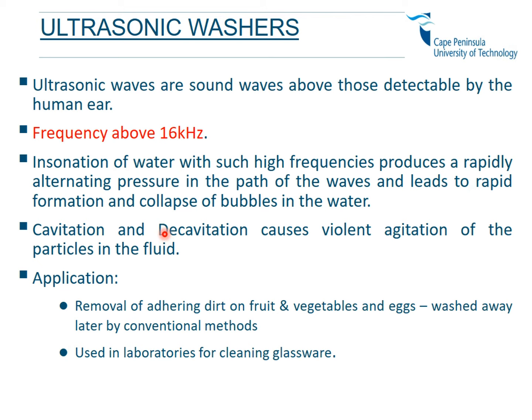The last method that we'll talk about is ultrasonic washers. This method makes use of ultrasonic waves, sounds which are above those detectable by the human ear. So the frequency should be above 16 kilohertz. Insonation of water with such high frequencies produces rapidly alternating pressure in the path of the waves and leads to rapid formation and collapse of bubbles in the water. So the cavitation and decavitation causes violent agitation of the particles in the fluid, and this is how the dirt is removed from the product.